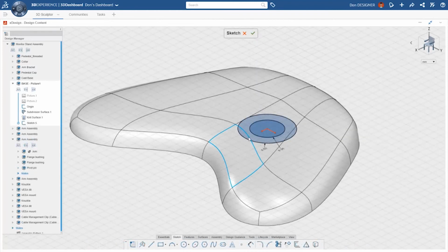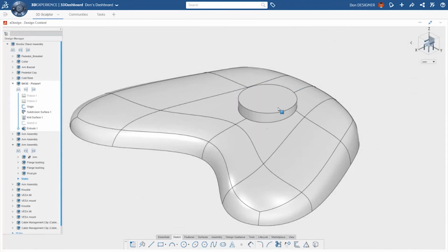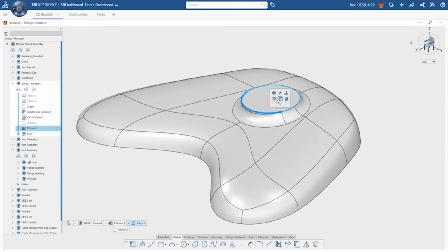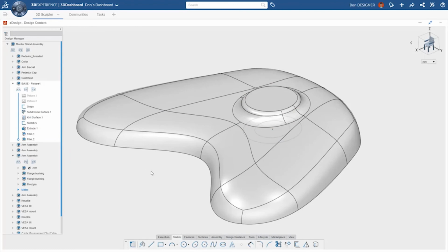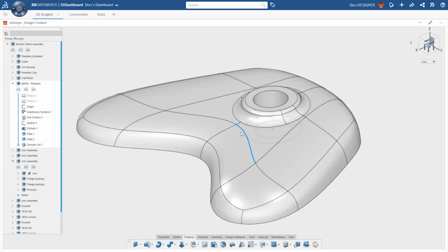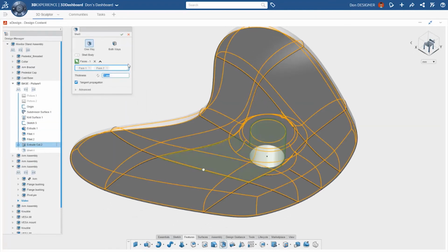Once we confirm the manufacturability, we want to finish the design. We can do this in xShape, but since these tools are fully compatible with each other, we can just switch apps on the fly and start working in xDesign to add the final boss cuts and also the shell features.